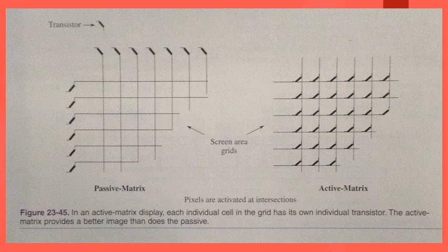The voltage is applied briefly and must rely on screen persistence and a fast refresh rate. Because current must travel along the row and column until it arrives at the designated pixel, response time is slow.